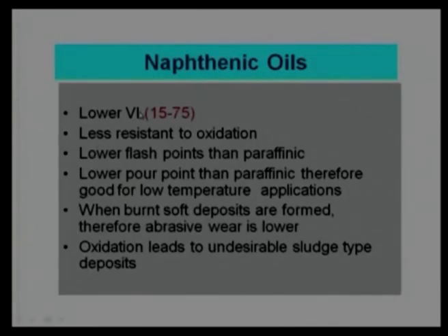Coming to the naphthenic oils, we say they have a relatively low VI, viscosity index. If I am very sure about the operating temperature, if I know the operating temperature is not going to change significantly, then I can choose naphthenic oils, particularly at low temperature applications.